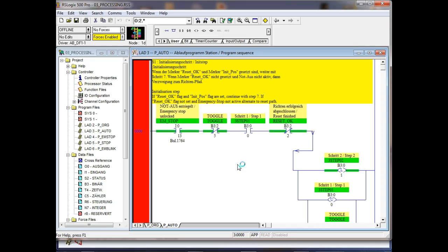So instead of me having to go in there and write that sucker every time, we can put them in a library and then import them in as a different file, which makes it really, really nice. And plus, the program is a lot easier to troubleshoot. If I'm having problems with my e-stop, instead of me trying to find that e-stop program inside a program that's 1,000 rungs long, I can write it as a subroutine, and then I can go and do that.